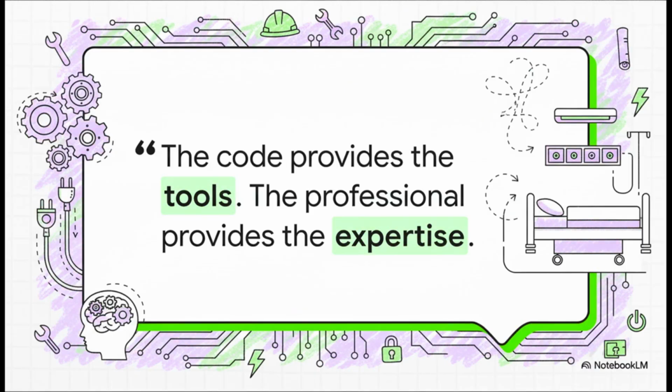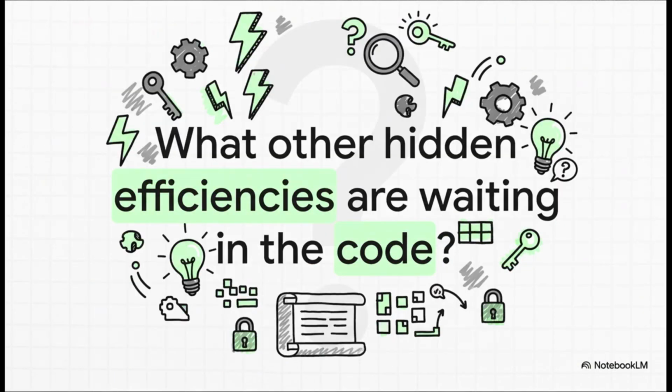And as we wrap this up, I keep coming back to where we started. The categorization of the space itself. The whole calculation, the 25 versus 50%, the 5K versus 10K, it all depends on whether you call a room category 2 or 3. Everything hinges on it. So the question to leave you with is this. What specific measurable criteria, things like life support or how invasive procedures, do the code writers use to draw that hard line between a category 2 general room and a category 3 procedural room? That's what justifies such a drastic difference in the electrical demand. Understanding that definition is the real first step to safety.